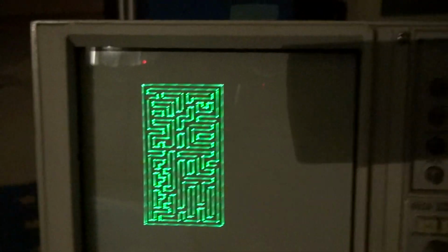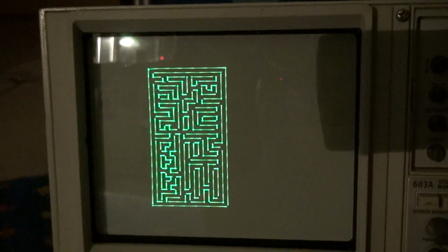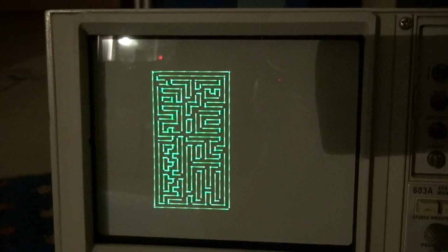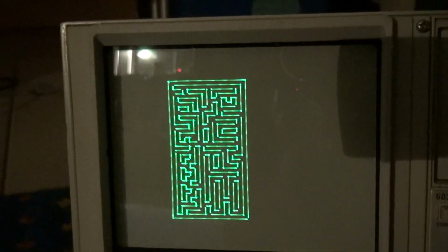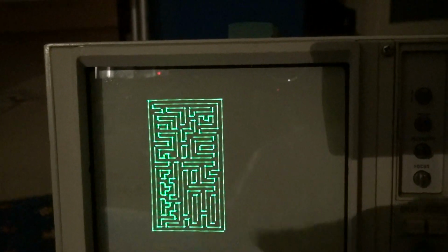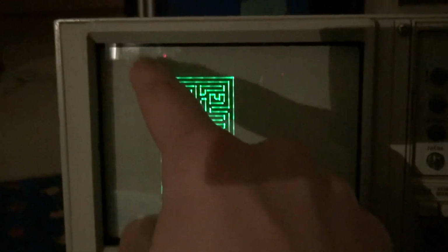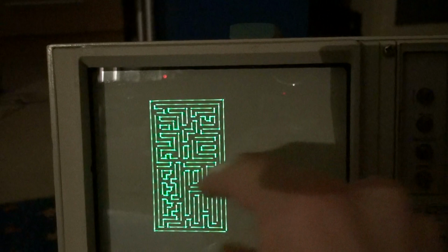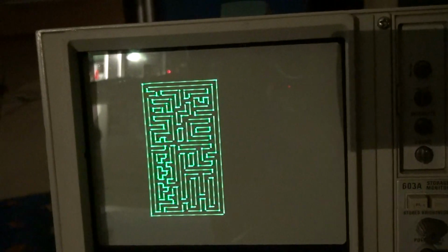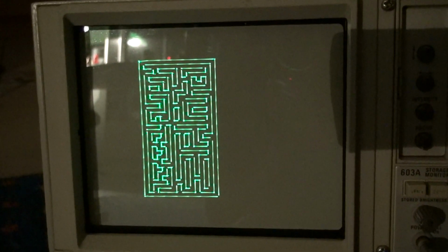So here we have something I call mosaic graphics. The way you use it is you issue an ASCII pattern, a pattern modeled as an ASCII string, to the VGI subsystem, and then it draws this mosaic pattern that is made out of squirts. I call it squirt because it's squirting in the Y direction over the screen and then in the X direction. That's basically an optimized raster screen. It goes like serpentines this way, so that's how it draws the squirts, and then it goes that way around. On a laser projector that's a little bit too much, I must confess. But here on the oscilloscope screen I must say it looks very, very nice.